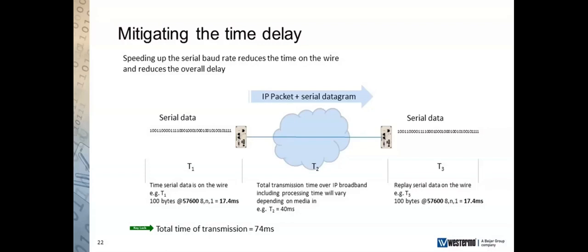It has a couple of benefits. One is that the timing is much smaller, but it also means that if you've got a big system that you're trying to get around and you're having problems reading enough data, and you maybe want to set your scan period to a much smaller value, you can now get a lot more data back in a shorter space of time than you could previously, so you can step your scan rates up. Now, that's one mitigation. That's just simply turning the serial speed up on the system.